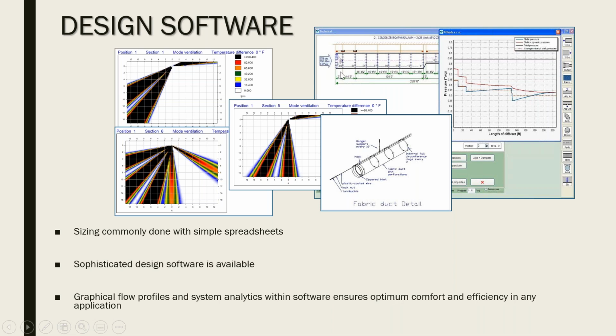you can see an arrow pointing into the fabric duct that's drawn there. It shows you the CFM, the inlet velocity, the static pressure. Some of these sheets will tell you exactly what is on the project, like the fabric, the installation method. It will tell you if you have ring supports or not. All of that will show on your data sheets. So engineers can be assured that they're getting properly working systems from the beginning all the way through to the end.